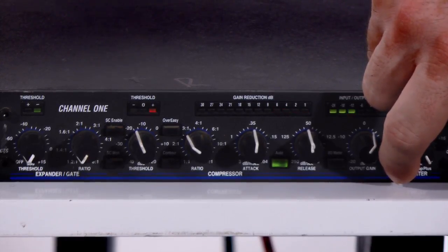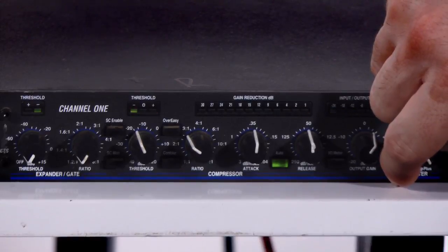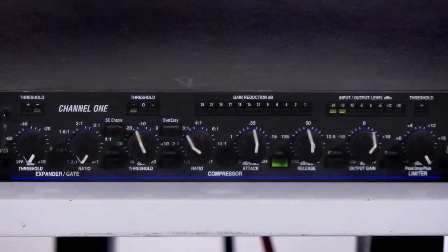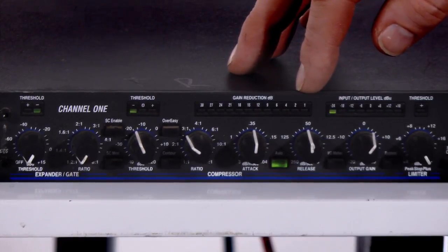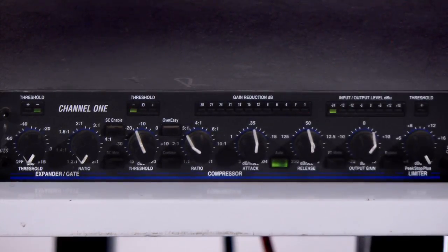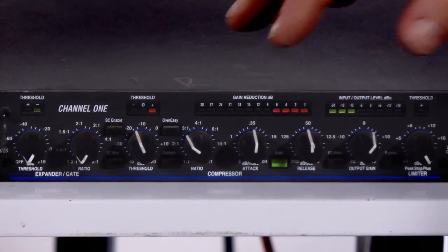Let me now repeat that test with the compressor engaged. The compressor is now engaged, and I'm speaking to you with minimum vocal effort. If we look to the gain reduction, we're only seeing minimal gain reduction. I will now increase to medium effort. And now notice that the dynamic range of my voice has not increased. We have capped this in some way. And even if I speak with increased vocal effort, the compressor will be dragging the volume down.